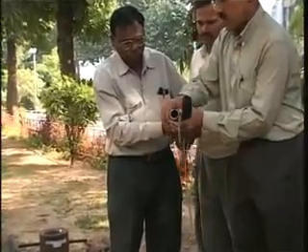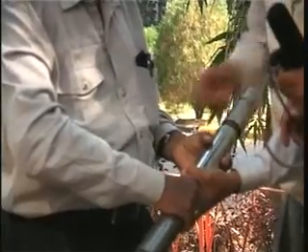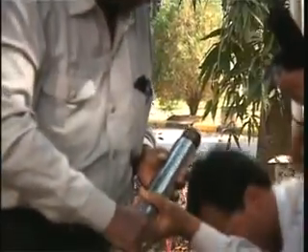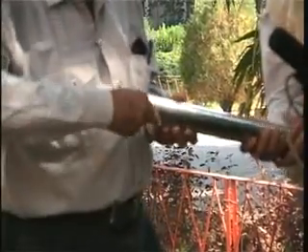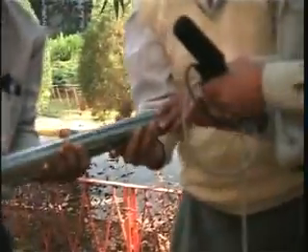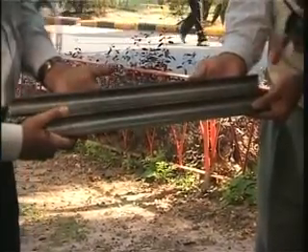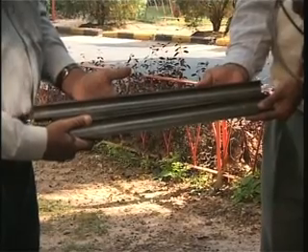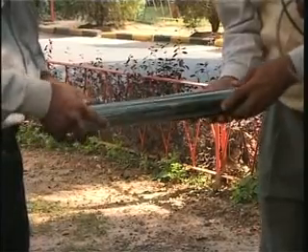Which comes off like that, and then the socket which connects the sampler to the SPT rod also comes off from the other side, and then the portion in between splits into two different parts, as you are going to see in a little bit. You need a rod to do that. And these are the two portions which split up like this, and then we assemble it and drive it into the ground to retrieve the soil sample. Okay, now we can reassemble it.